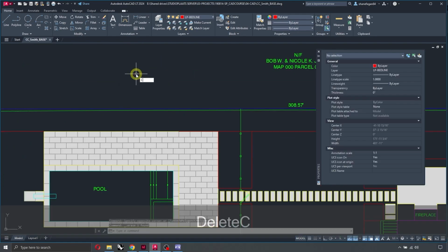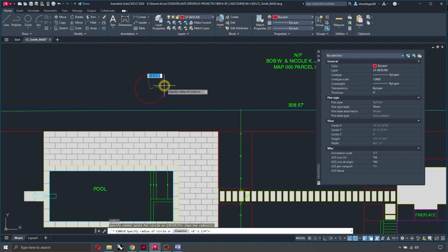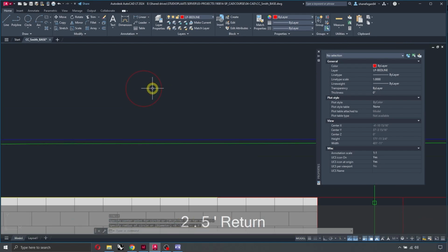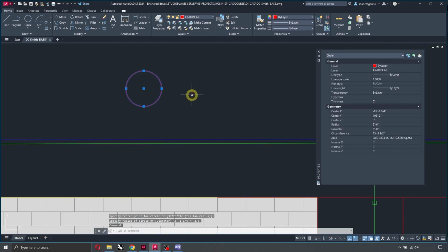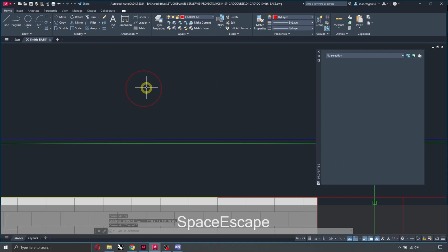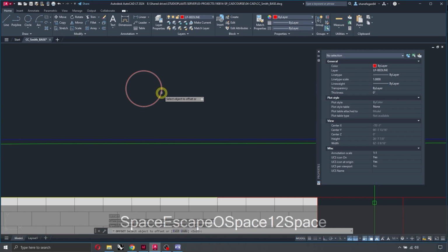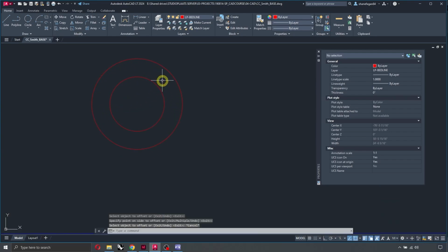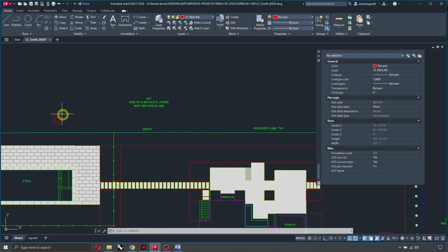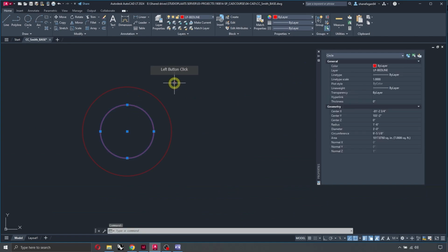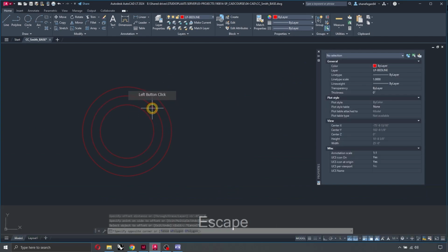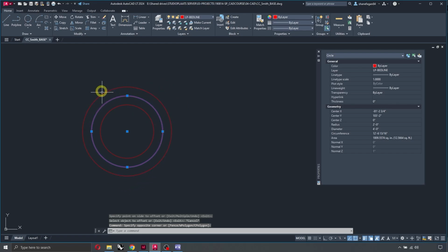Let's say we've got a fire pit that's 5 feet across, so we've got a 2.5 foot radius. And we've got a 12-inch wall. So let's do O for offset, 12 for our distance. Now to get your takeoff for walls, typically you'll use the center line. That accounts for both sides. If you have a big, long, curvy wall, you use the center line for the takeoff. So it actually offset that 6 inches. Let's say I had a cap on the stone. When I was ordering my cap, I'd have about 12.5 feet for my order on the cap for that stone.